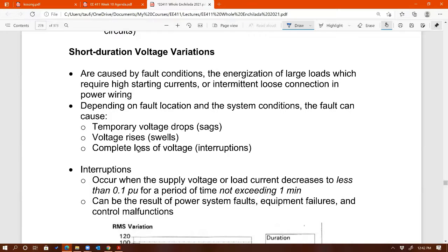But because the step down transformer near our house has lower voltage and relatively higher current. That's right, yes. But if you see the effect on the primary side of the distribution transformer, I don't think that will see the effect at all, right? It's because the primary side of the transformer is connected to so many other houses, so it's a bigger electrical system.